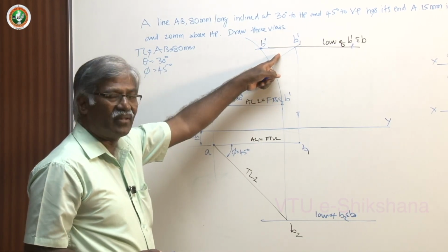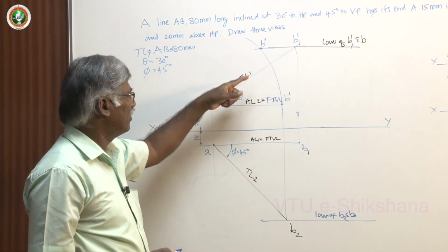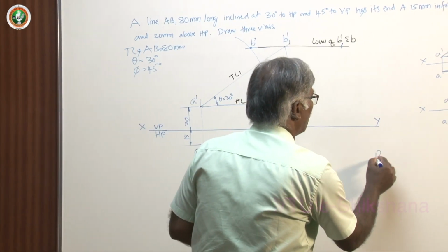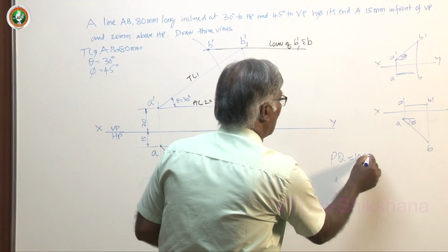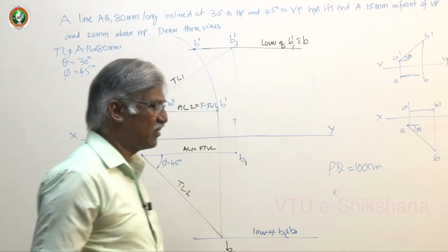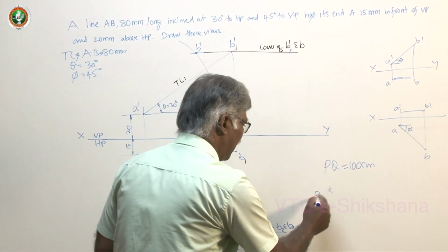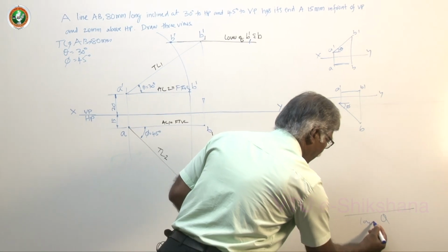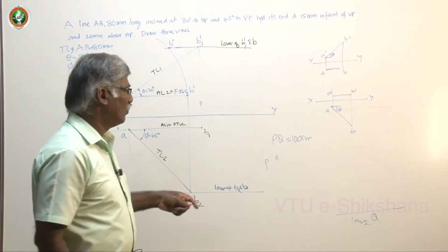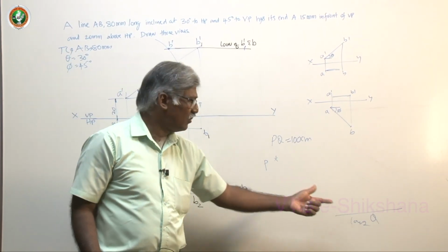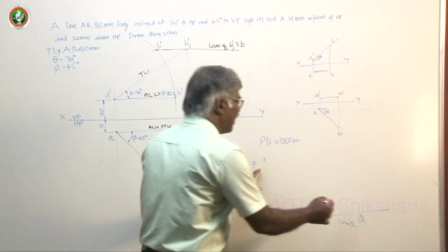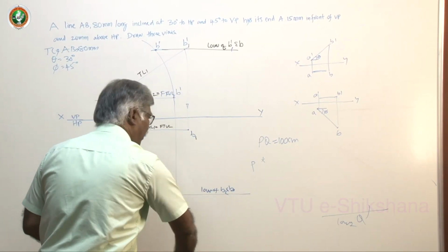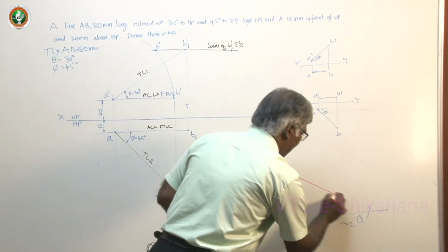Here is the path, and then rotate. To make you understand simply, I have PQ equal to 100 millimeters, and you have point P here, and the locus of Q is here. This is the locus of Q. Now, how to mark Q? Take 100 mm equal to radius, draw an arc. You will get the final required line and orientation.